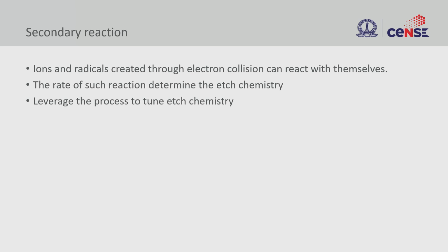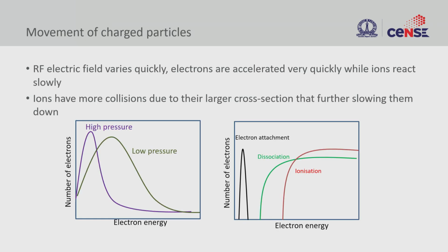Okay, so we need to look at the chemical etch chemistry particularly, right? What is the forward reaction, what is the backward reaction, and how do we arrest the backward reaction in some cases, so that you create enough number of radicals for etching, right? In some cases backward reactions need to be done to create some solid products or gases, whatever you need, but one needs to understand the etch chemistry before you change your gas flow or work with your plasma.